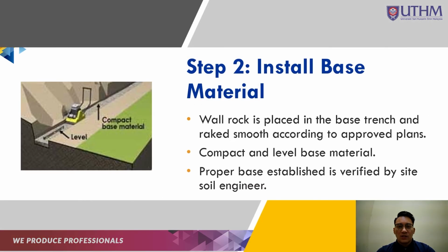And step 2 is install base material. Wall rock is placed in the base trench and raked smooth according to approved plans. Then we compact the level base material, and finally, the proper base established is verified by the site soil engineer.